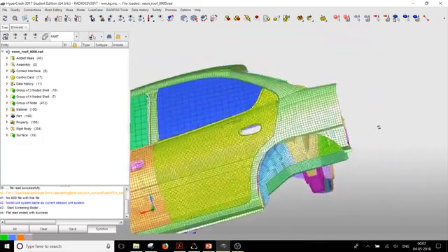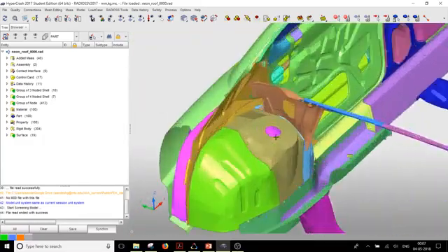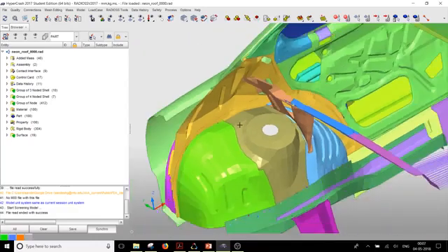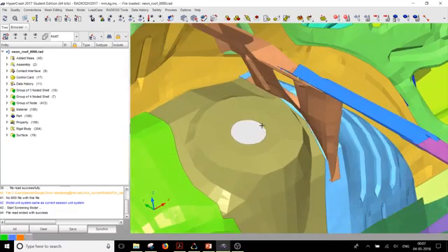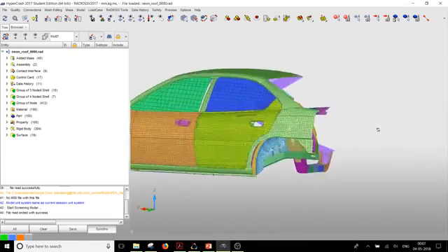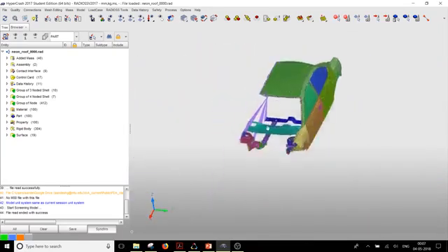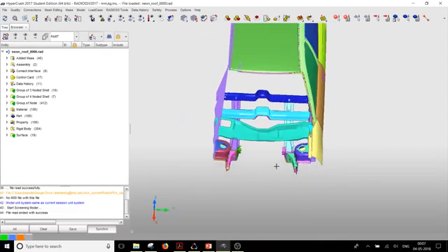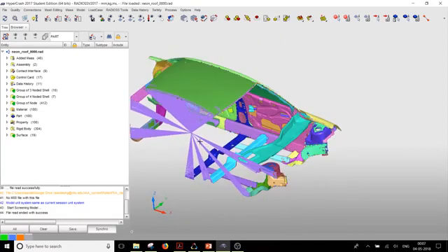But now since we don't have the wheels or the shock absorbers, we have to assume that the displacement of these nodes, at least in Z, is 0. So you'll have to create a rigid body over here. The master of the rigid body should be given a boundary condition that it doesn't move in Z direction at all, the global Z at all. So there are 3 shock towers as such. There is first, second and third, and all of them have to have this similar boundary condition.